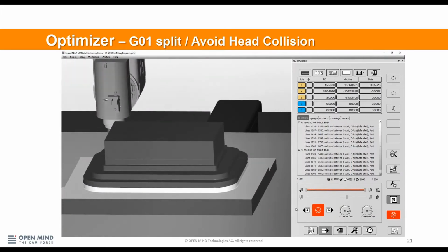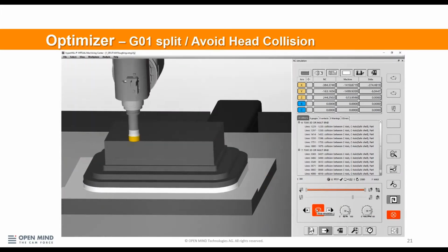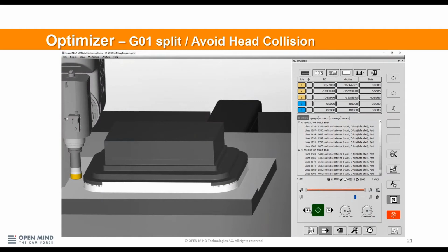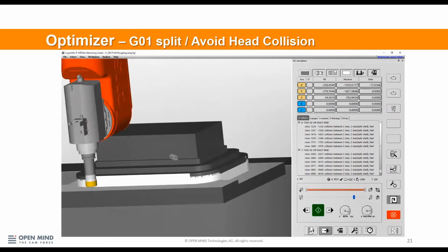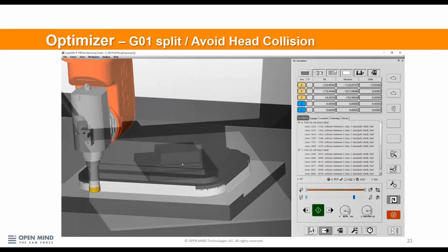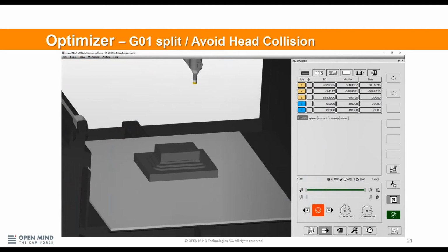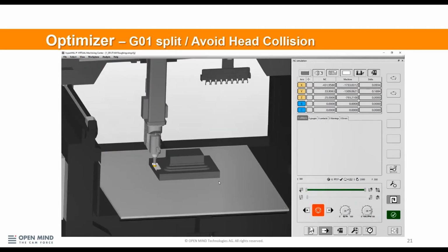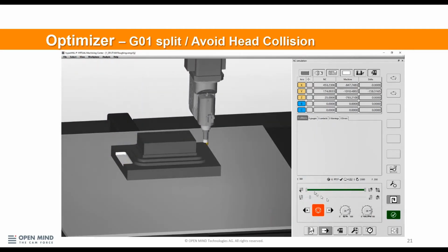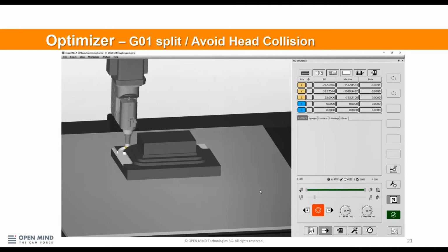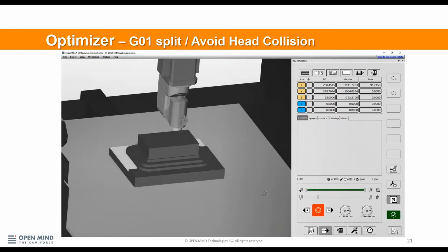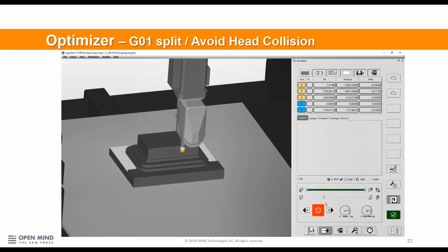Do we split the tool path and do all of the programming work to shift the head in multiple orientations, track the stock to make sure we didn't miss anything? This is a lot of work. When the NC optimization is performed in the post run, it sees that we can machine 3 of these 4 sides and then will automatically rotate the C axis to avoid collision with our machine head.